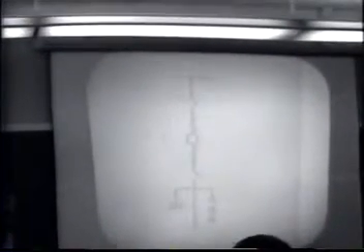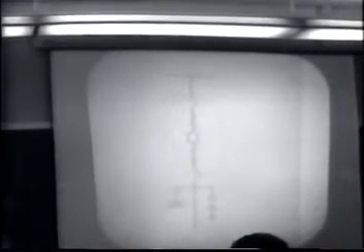Each of these devices will be rated according to the voltage level at which they can operate and the current that they can carry continuously. In the case of the disconnect switches, the circuit breaker will be rated at a voltage rating. It will have a continuous current rating, and it will have an interrupting rating. That is the magnitude of the fault that it is capable of interrupting.